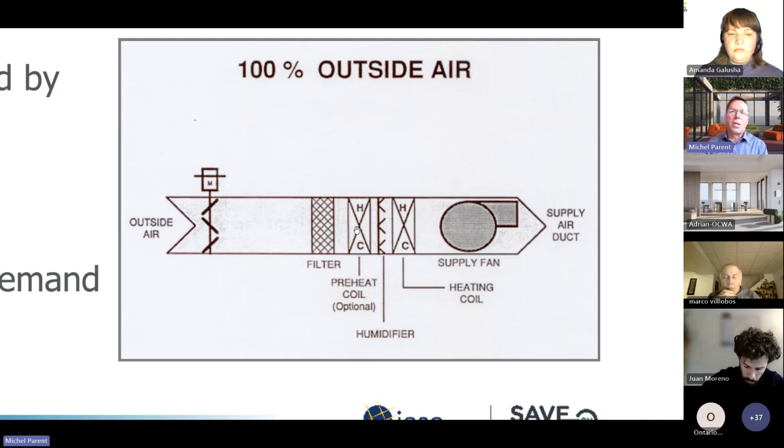And that changes quite a bit of things when you do your baselining, which we're going to see shortly, and when you do your estimate of energy savings. So always look what controls those coils. If it had a cooling coil, what controls that cooling coil? If it's a duct temperature sensor, then typically, there's exception, but it's what we call a cold deck system.